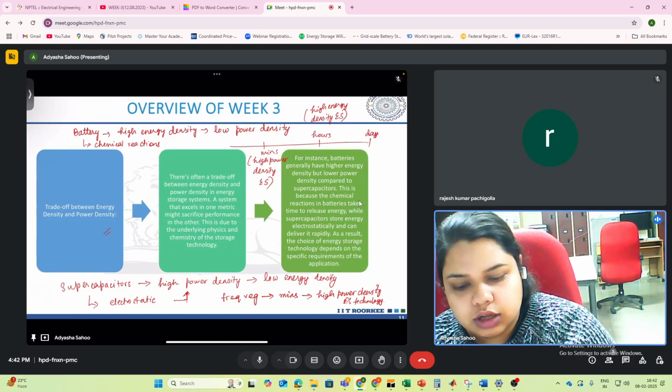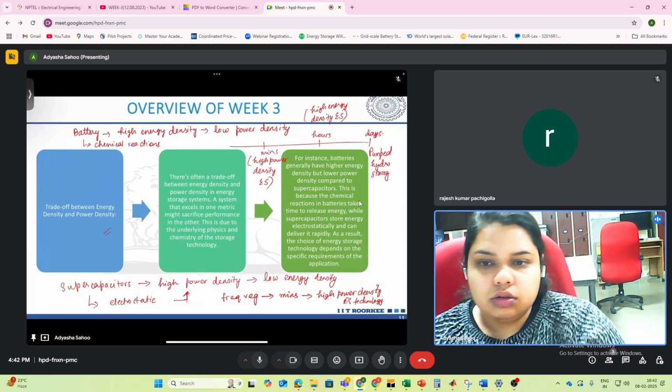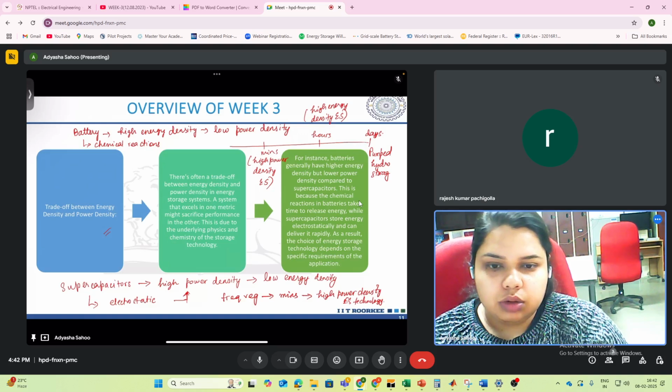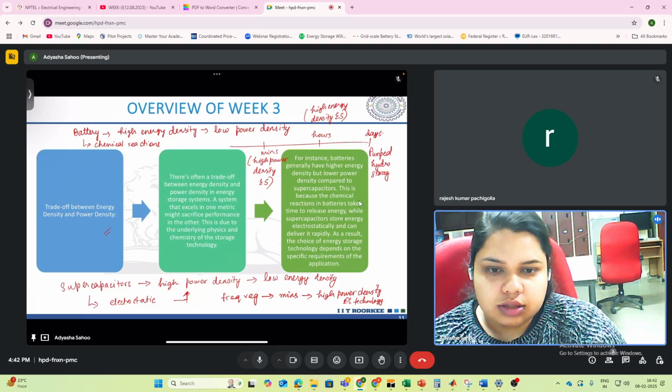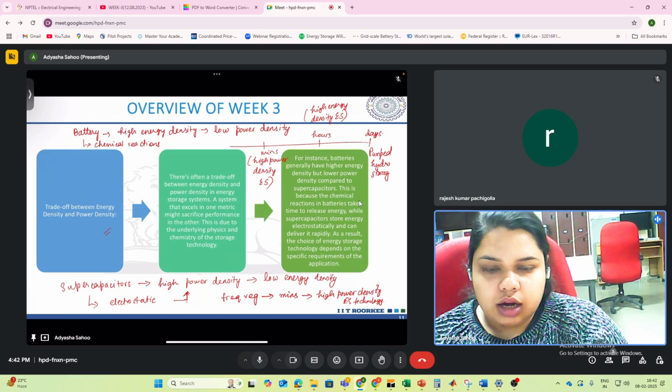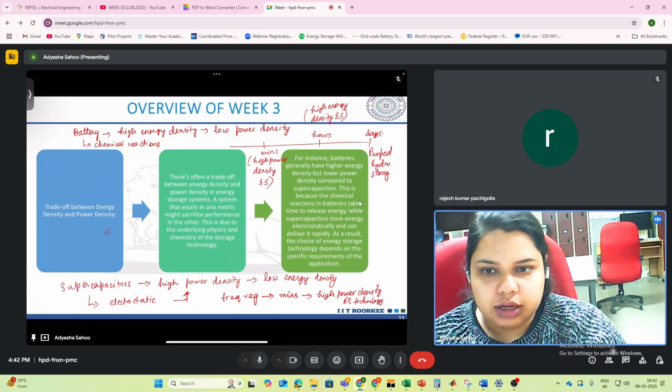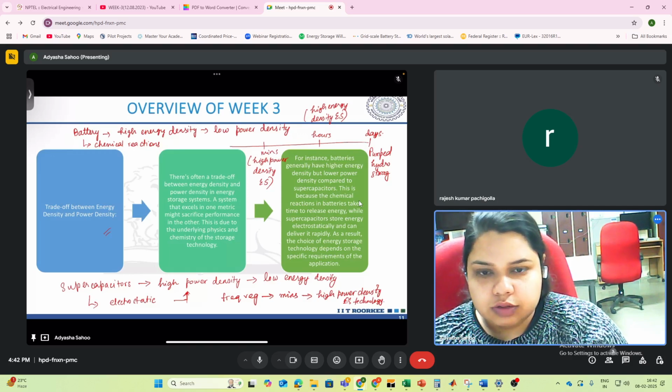The storage technology that we generally used earlier was pumped hydro storage. So pumped hydro, we know that whenever there was excess rainfall during the rainy season, we store the excess water in a dam or reservoir, and whenever the monsoon season has passed and we have summer, then the reservoir water is used to drive the hydro power plant and supply electricity. So hence it is a kind of seasonal storage. You store it for very long hours. So earlier it was pumped hydro storage.